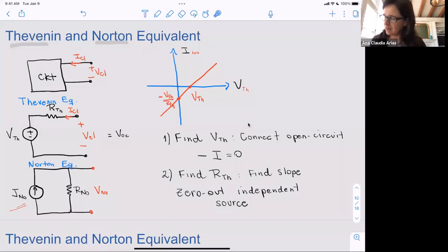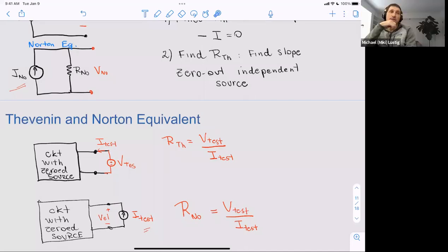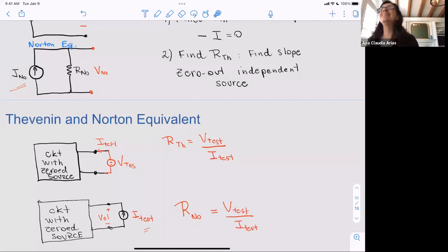Then when you apply this external voltage and this external current, you know exactly that's what is inside here. There is no contribution from another source. It's only the source that you're using to test. Did I answer your question? Great. All right. Put this in your pocket because this is something that you're going to use a lot to analyze circuits. Clear?